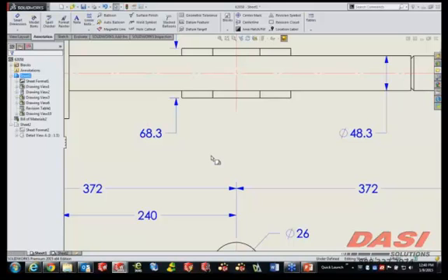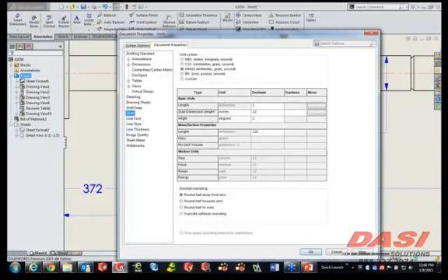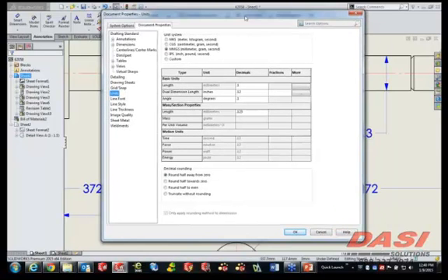Well, there's other people that don't necessarily round that way, and you might not be aware of these disciplines, but they are out there. If you go to your unit switcher and simply go to Edit Units, it's the quick way to get to Tools, Options, and Document Properties. But we have new rounding options here that allow us to round half away from 0 or round half towards 0, which is going to be now half up or half down, and then round half to even, the next even number, or truncate without rounding.